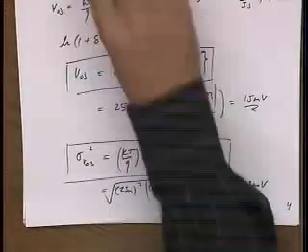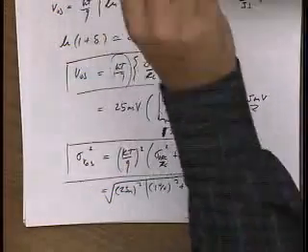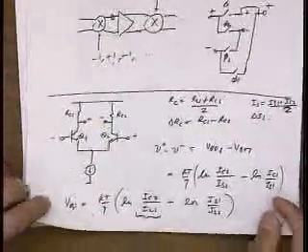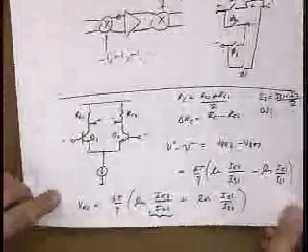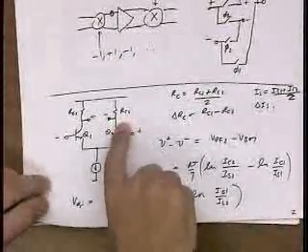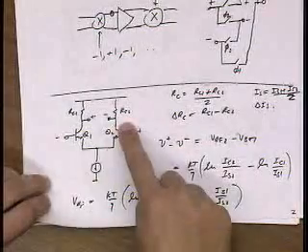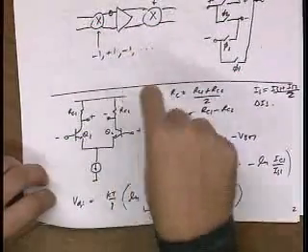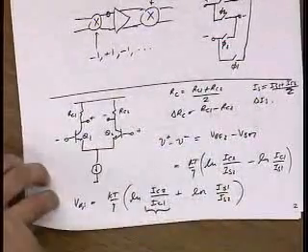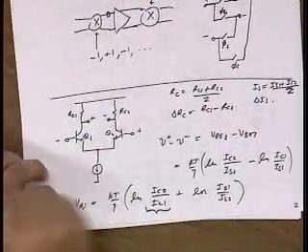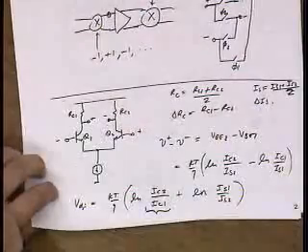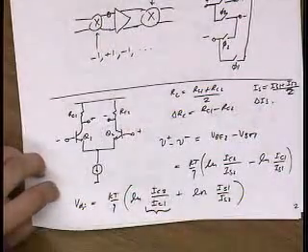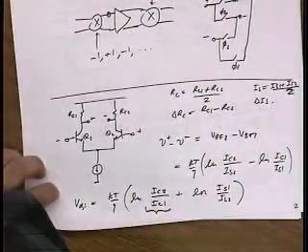Just a note on trimming, a lot of people actually... integrated circuit, right? You can't really vary this resistor with a screwdriver. So how would you vary it? Yeah, you would laser trim it. You'd actually have a bunch of resistors in parallel, and then you would shoot a laser at those resistor contacts and one by one remove resistors until you get the right value of resistance.